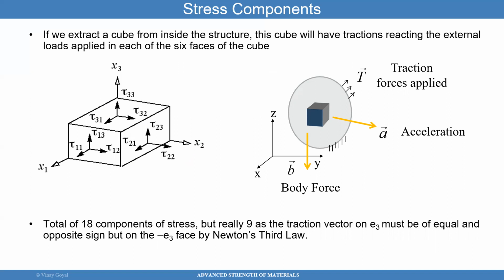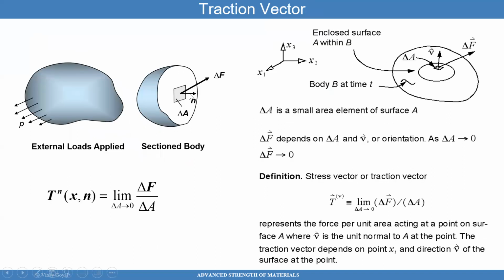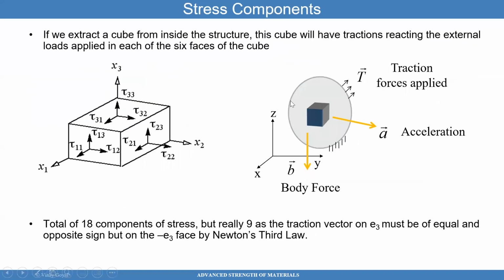When I think of trying to determine where the system is going to fail, I want to understand how these tractions vary across every point in the material. And so what I want to do is construct a little cube inside the volume of material.